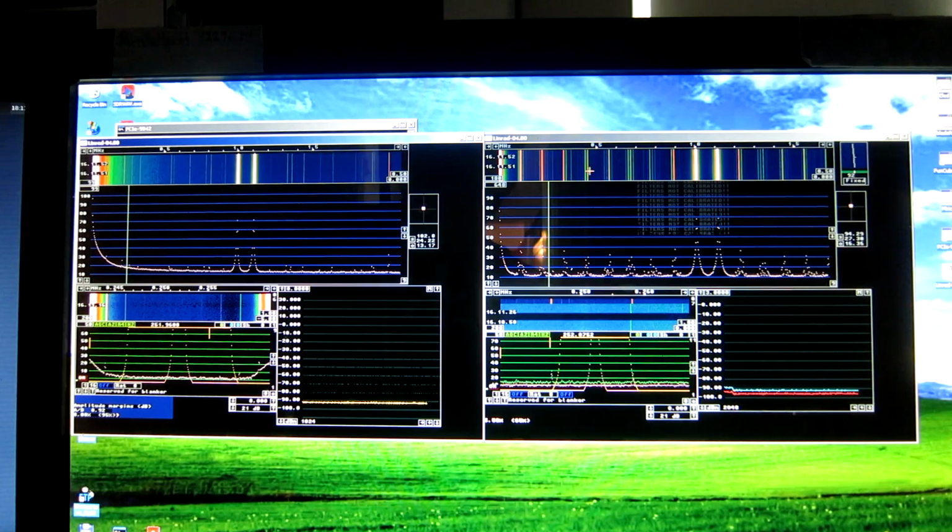So it's quite clear that the bladeRF AD converter is not suitable to use as a medium wave receiver, or as a receiver at all, presumably, because although it can sample at 40 megahertz and give us 20 megahertz bandwidth, the performance is mediocre.